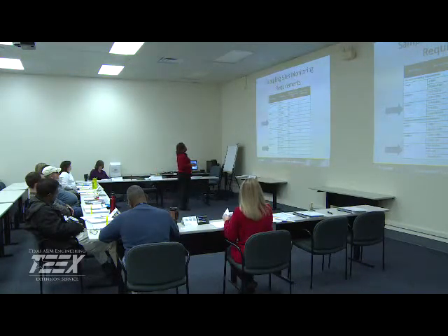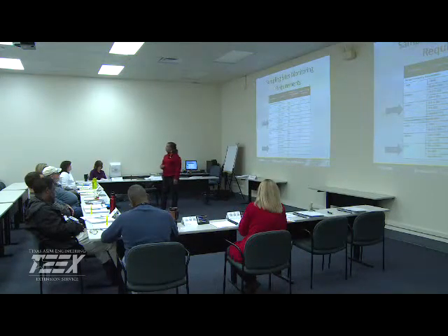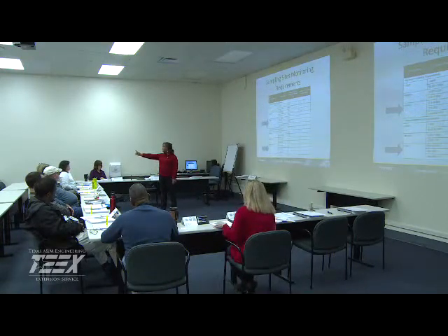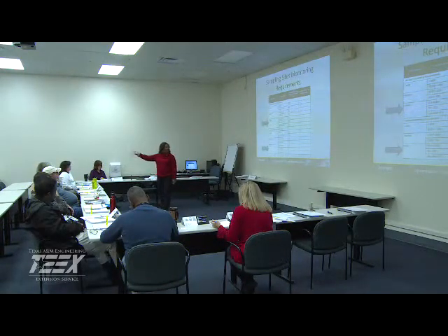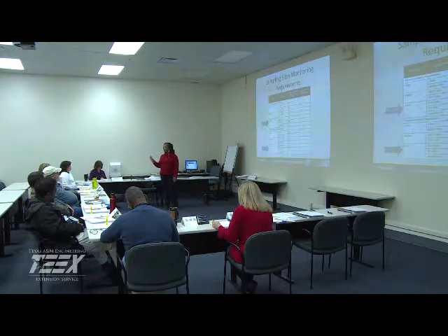Now for reduced monitoring, how can I get on it? I'm almost cutting my sample sites in half for at least 2 of the population sizes we're concerned with. So what do I need to do to be part of reduced monitoring? I have to make sure I'm underneath the action level or maximum contaminant level, and that I can demonstrate this is not an issue. Then I can go on reduced monitoring.